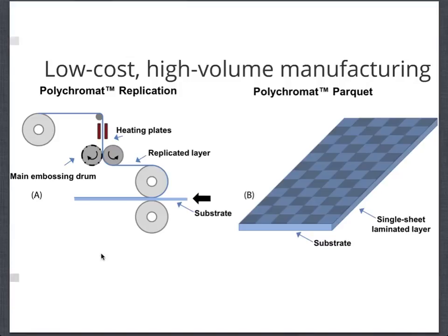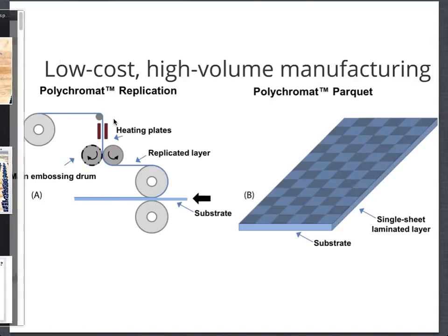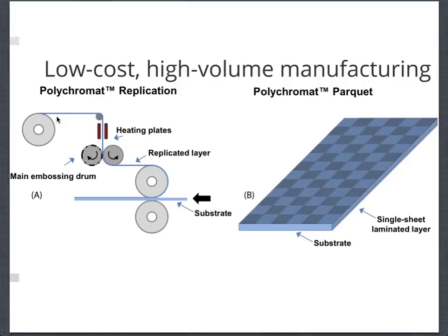to write each device. For photovoltaic modules we want large numbers of those devices. So how can we do that? There are actually a couple of approaches we can follow, but here is an example of a roll-to-roll embossing process. The basic idea is that you have a film, say a film of a thermoplastic, polycarbonate or polystyrene or something like that.